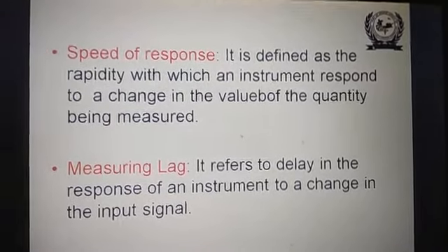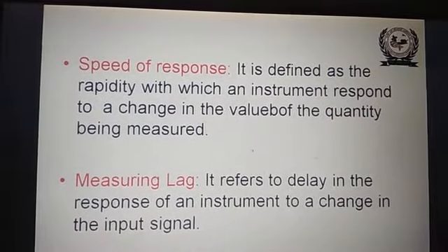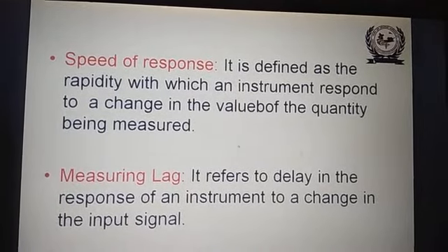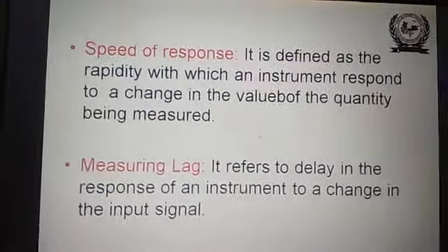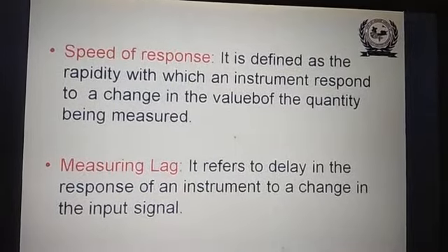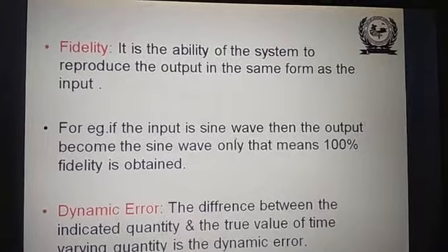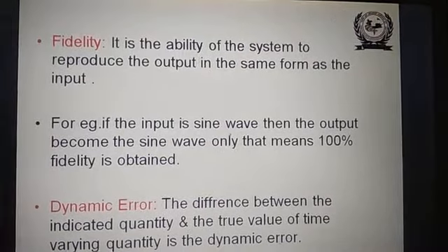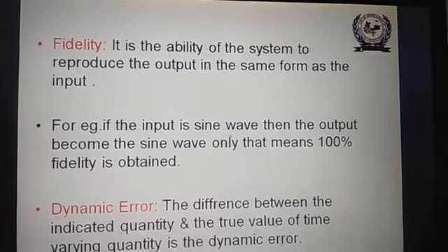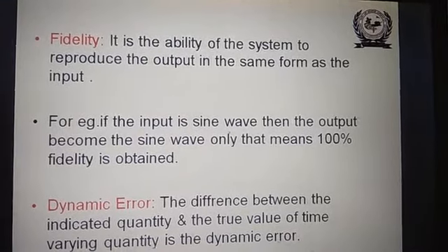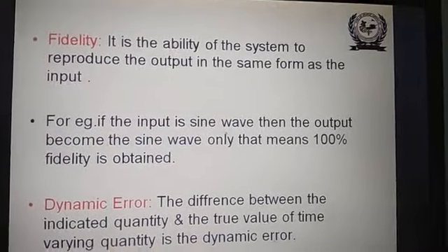Then lag, measuring lag. It refers to delay in the response of an instrument to a change in the input signal. So if we change the input signal and there is a delay in the output, it's called measuring lag. Fidelity. It is the ability of the system to produce the output in the same form as the input. It's called fidelity.